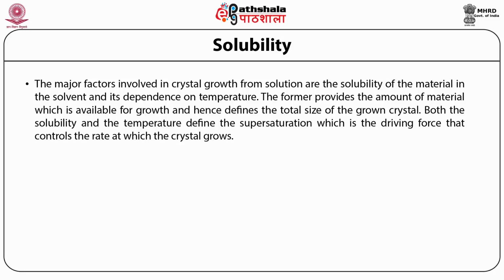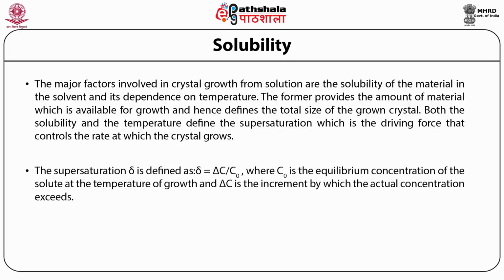Both the solubility and the temperature define the supersaturation, which is the driving force that controls the rate at which the crystal grows. The supersaturation delta is defined as delta = ΔC/C0, where C0 is the equilibrium concentration of the solute at the temperature of growth and ΔC is the increment by which the actual concentration exceeds this.